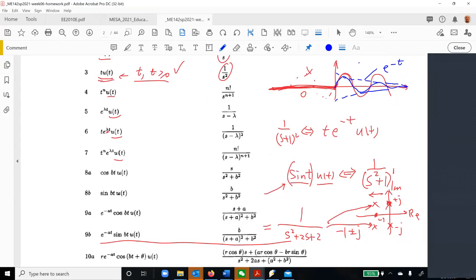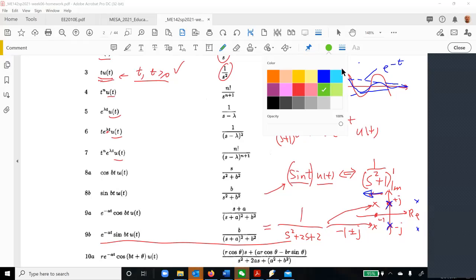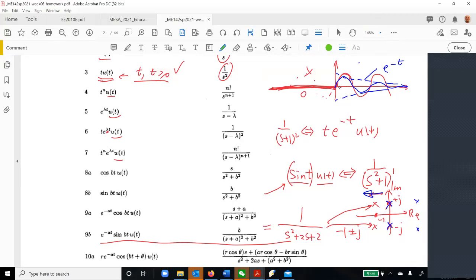When you move the poles towards the left, you have more damping. If you just stay on the imaginary axis, you have a sustained sinusoid: the amplitude will not go up or down, not divergent, not convergent. You can imagine if you put it on the right side, then you have something that blows up, the sinusoid will have something.